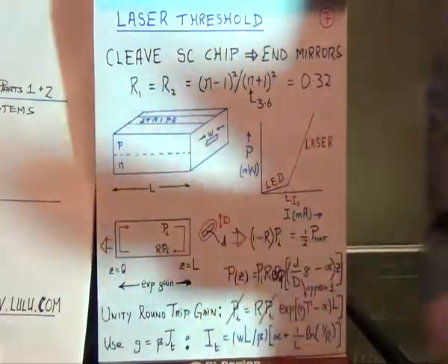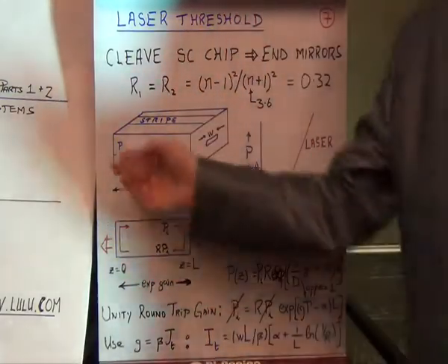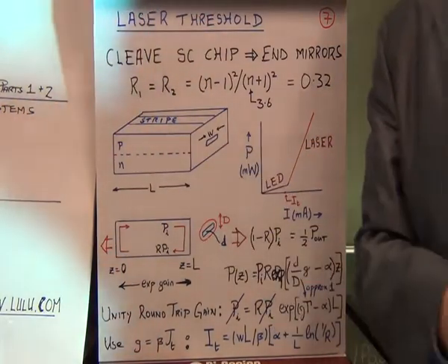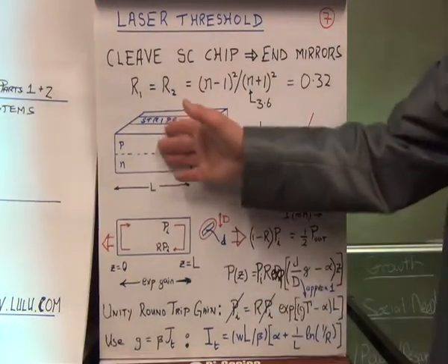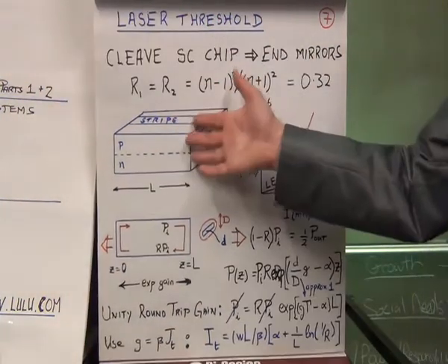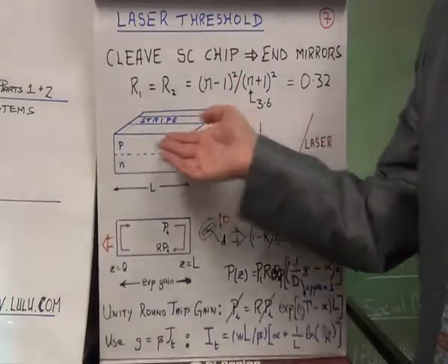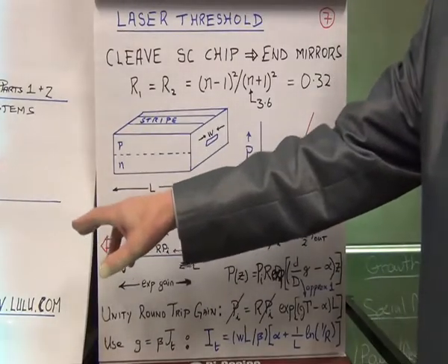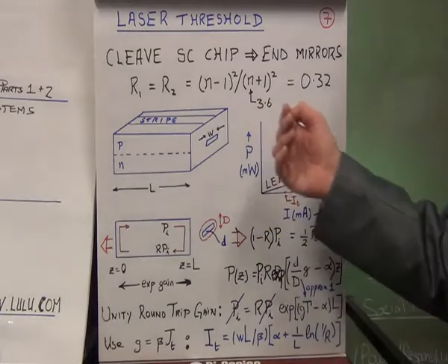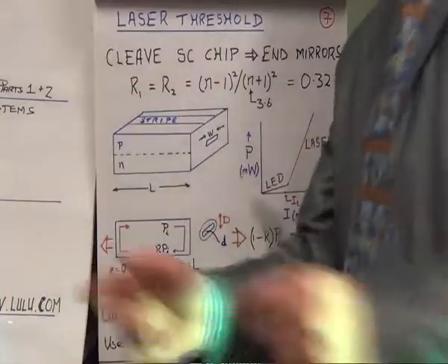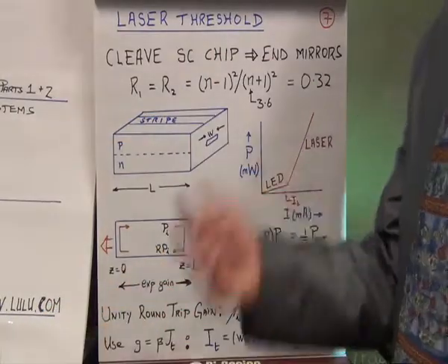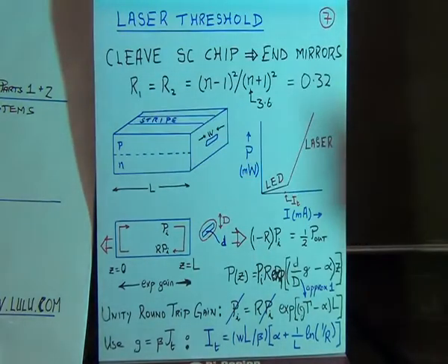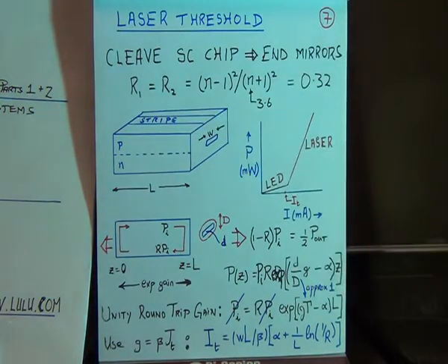The other output, you can make great use of it too in engineering. You can focus it onto a photodiode. For example, you can use it as a monitor. If the laser dies, you're in a telephone exchange, you have an array of 100 of these for WDM, say, and one of the 100 goes down, the photodiode sets off an alarm. And the whole system is programmed so that all the internet packet data are rerouted to another one of the WDM channels, while the engineer is getting at this transmitter to identify what the problem is or replace it. So there's no downtime when these things happen.